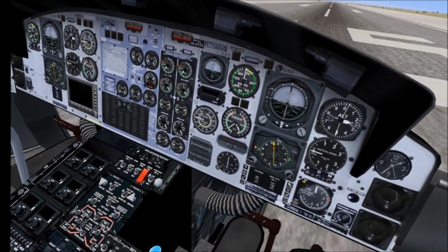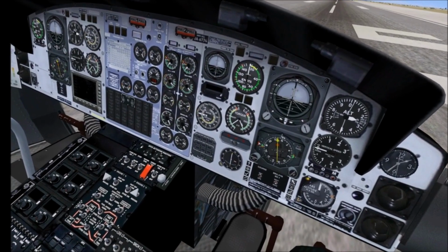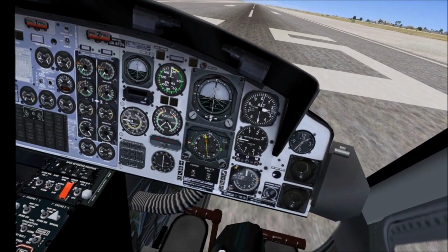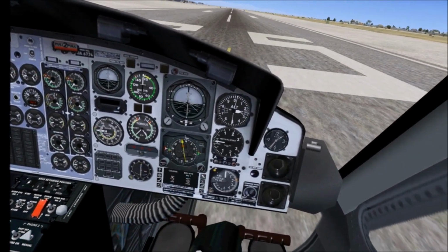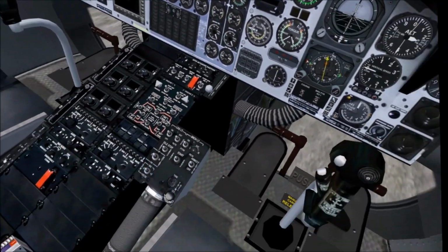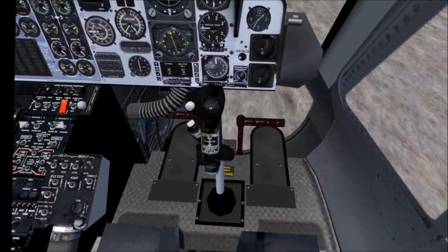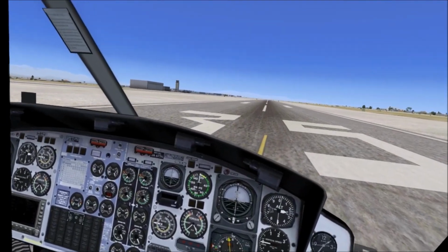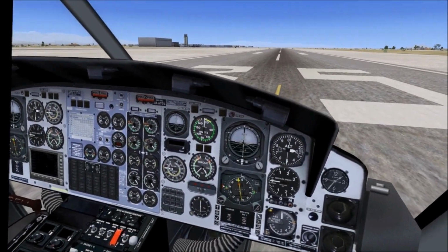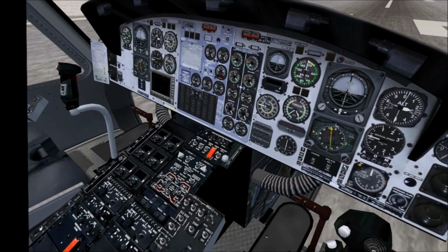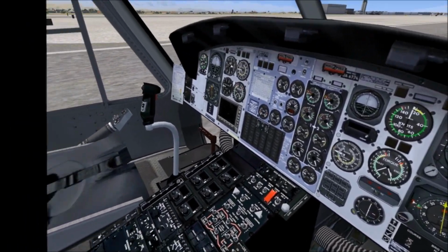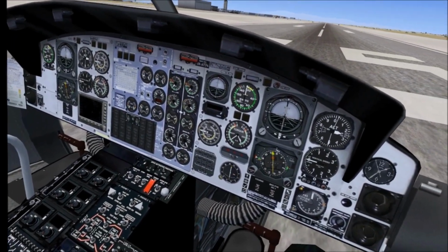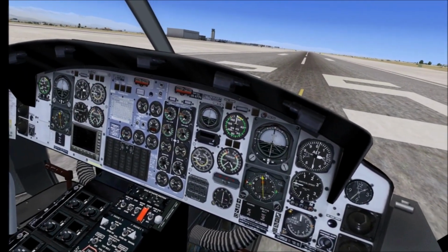And what we're looking for is we're going to use 70 knots and torque of 90%. And with that, we should see a rate of climb of 2,200 feet per minute dual engine. Okay, so that's what we're searching for. So if it's close to that, we'll call it good. If it's more than that, which I suspect it probably will be, but we'll see, because FSX aircraft usually tend to be overpowered, but we're just going to set those parameters and see what we get.